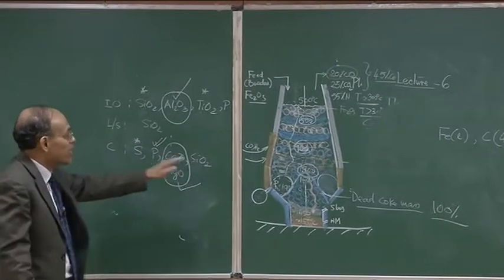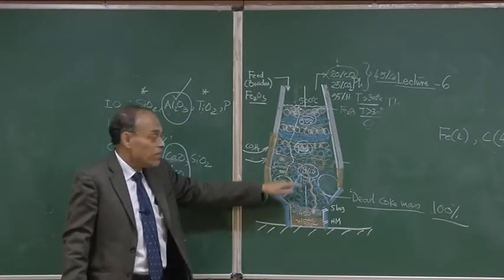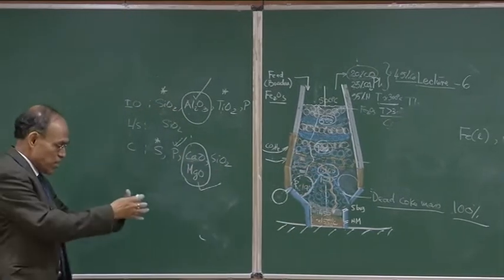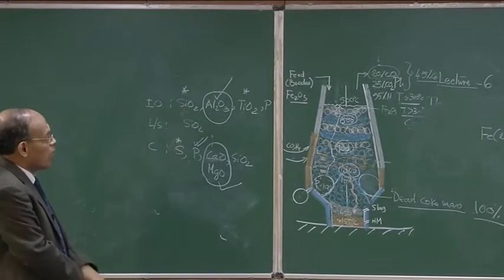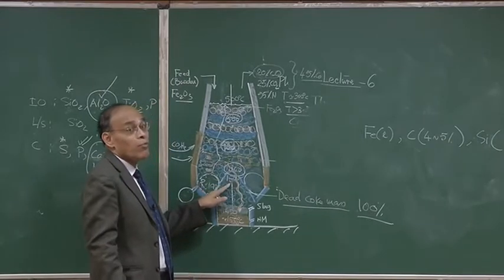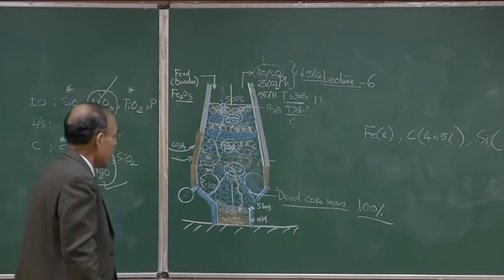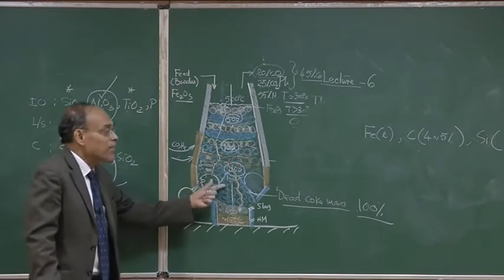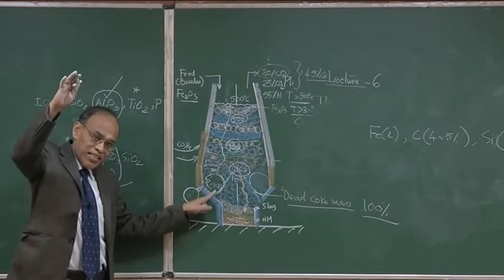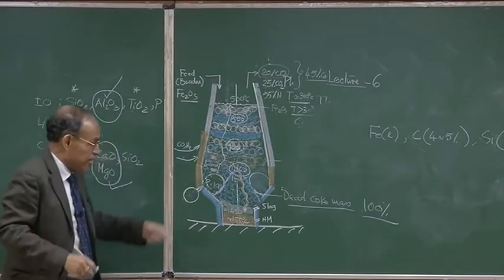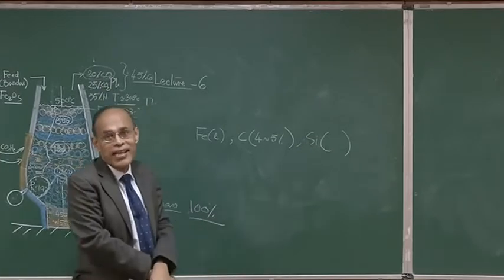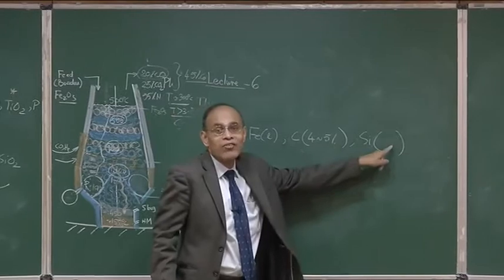So, that reaction will take place basically at the lower part of the furnace, because the silicon-oxygen bond is extremely strong. So, we can say that silica to silicon reduction will take place in the lower part of the furnace, where we have more intense carbon monoxide and higher temperature. Depending on the temperature, if the blast furnace raceway temperature is increased beyond 2200 degree centigrade, or 1900 degree centigrade, we can see more reduction of silica taking place, and as a result the hot metal silicon content can increase.